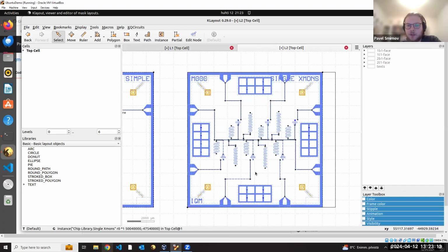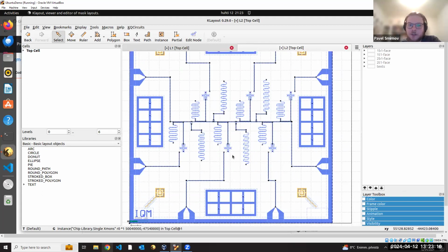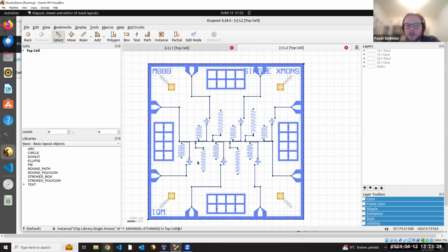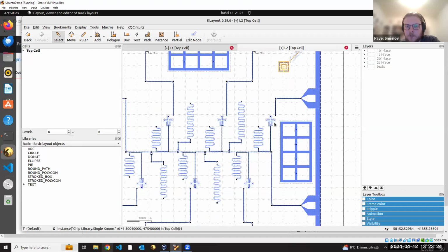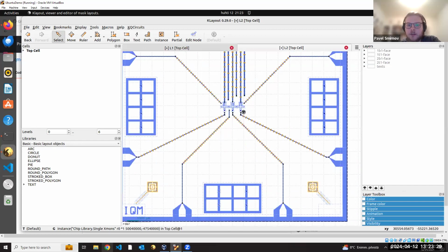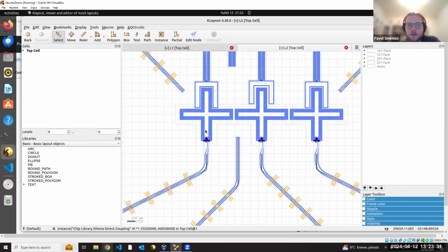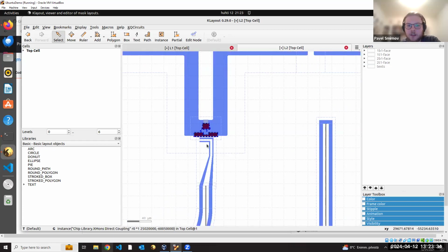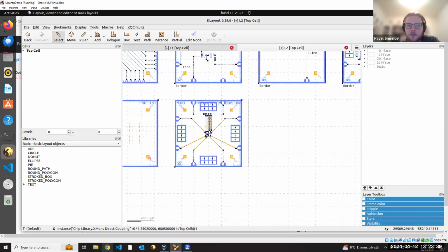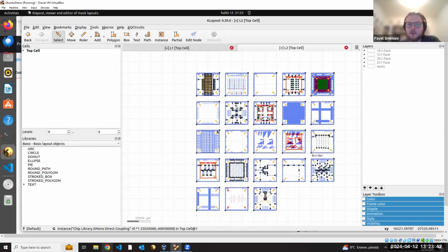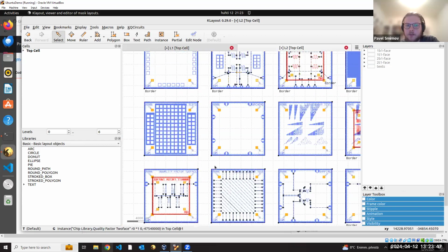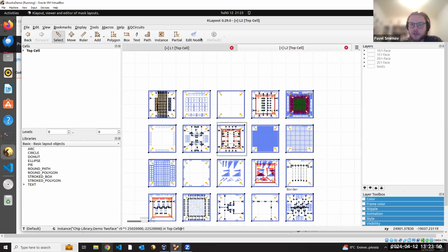But here, I guess, is an example of an actual chip with qubits that can be controlled. So it looks something like this. In this device, there are 6 qubits here. I think in this one, there's actually a drive line, but also a flux line, a waveguide that connects to this squid. So you can also control the flux of these qubits. So I recommend to check out what these chips do, if they could be useful for you.